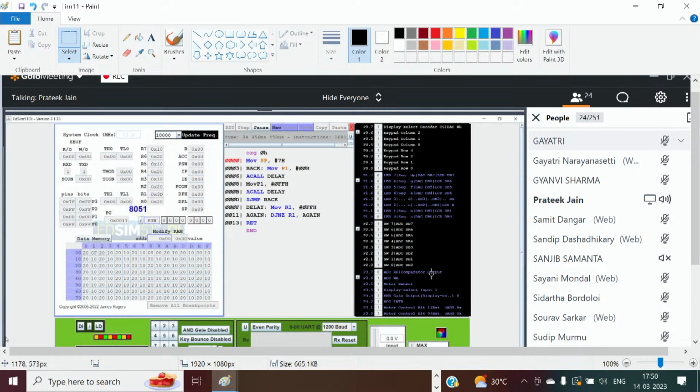Again for R5 it is in serial manner because the LED will be blinking and toggling over here. So this is DJNZ R5, with its label. It is in sequence. Right now you can see for the 1 and for the 2, one after the other, and we have to keep it, and this time it is to be returned with RET, and now the code is over, END.